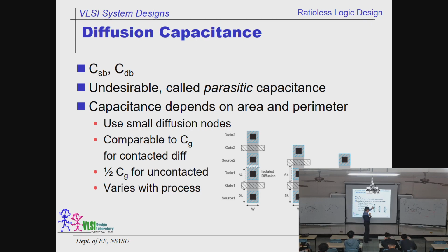Why don't we just merge these two together? Because all we need is just a short circuit. That's all. So a better designer will merge these two contacts together, making the signal going up and going down in the same hole, which will save one contact. But it's still redundant. Why do you want to set it up and set it down? It's ridiculous. It's just running for nothing.